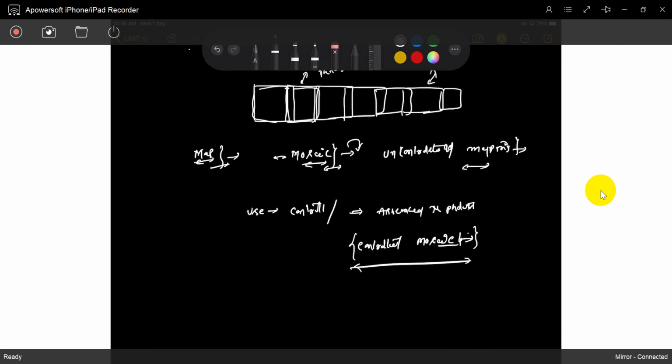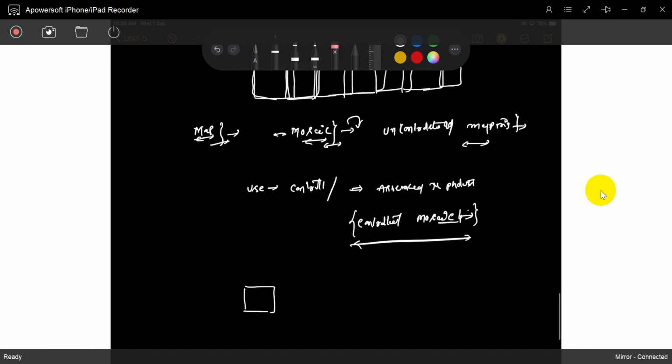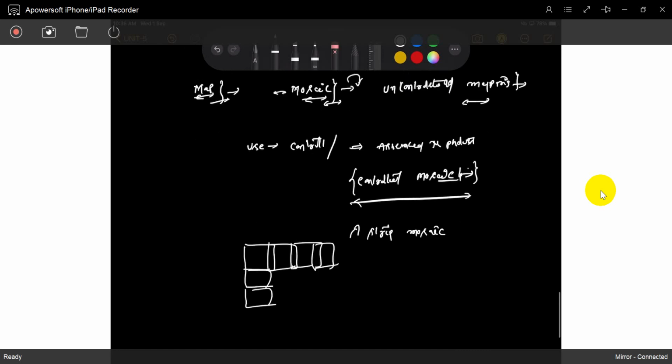If you use only one line, it is called a strip mosaic. We can assemble those strips and you will get the full map. That is called a strip mosaic. Take one strip, second strip, third strip, and we can assemble every strip. Later we will get the total map of that picture. So these are the terms: photograph and mosaic, what is controlled and uncontrolled mosaic, and strip mosaic.